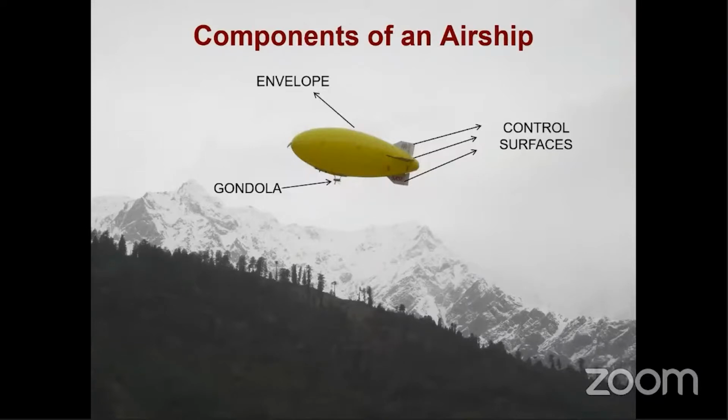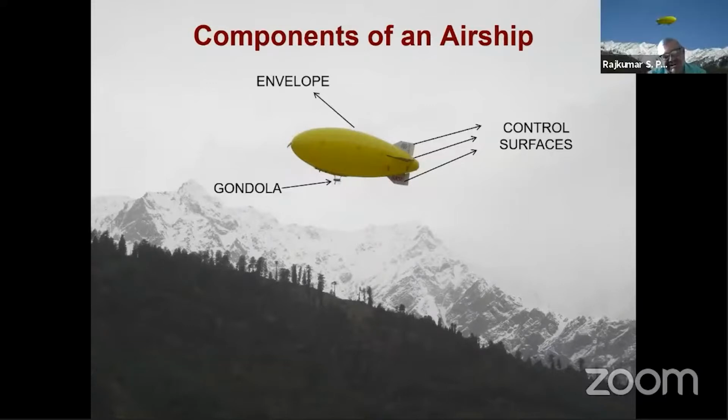Lift force. No, not only lift force. There will be a normal reaction acting on it, and when we take it into components along and normal to the ambient relative wind, we call it lift and drag forces. So some additional lift will be acting on this airship as it moves forward. That lift is called dynamic lift, and the lift which comes because of buoyancy, even when it is stationary, is called static lift. So airships have two kinds of lift: buoyant lift, which is maybe 80%, 90%, and dynamic lift, which will be 15 to 20% generally.